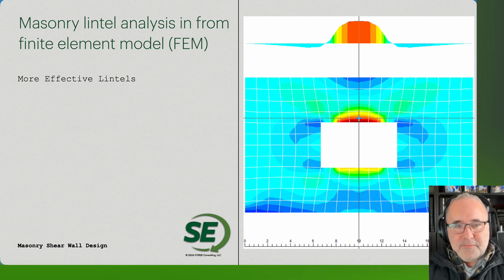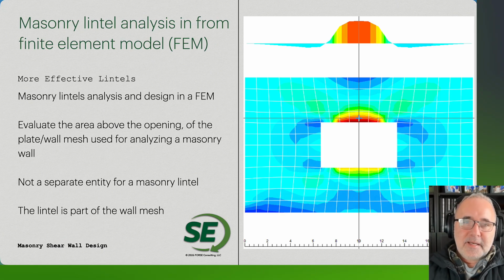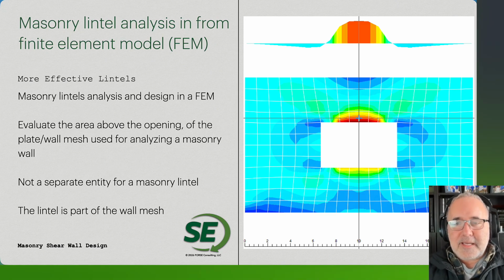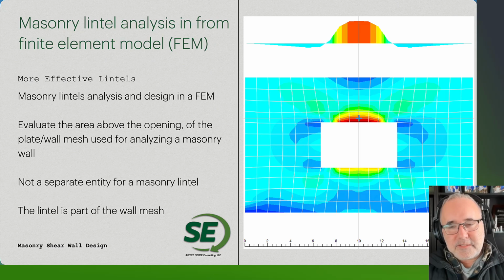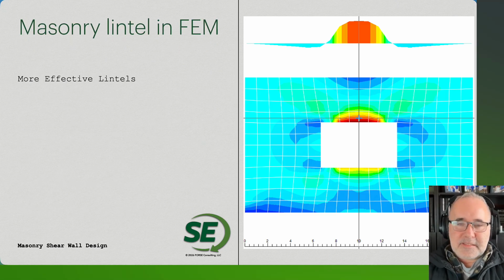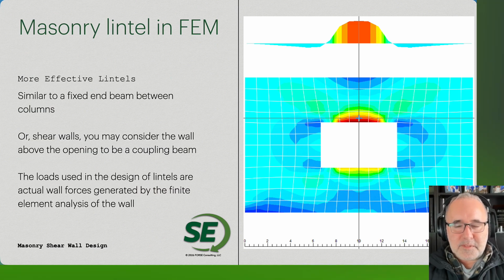Certainly, again, having the right finite element analysis so that we can look at the overall forces and stresses. We can look at the moment capacities, moment demands on each area of the lintel. We can see that the lintel elements in these perforated shear walls are going to be meshed wall elements that are going to tie into and be fixed to the meshed wall elements for the jambs and wall areas on each side of the opening. But again, we're going to have a lot more capacity in these designs. We're going to have a lot better understanding for what the overall lintel design would look like.